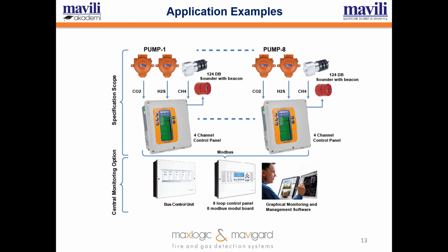Our aim here was to implement a project where, if the explosive or poisonous gas level inside is outside of normal, it's not allowed to enter inside. In addition, in this project, the data of these devices were monitored over the panels by using as many Modbus cards as the panels on which each pump is controlled. And the panels were monitored and controlled via supervisor software.